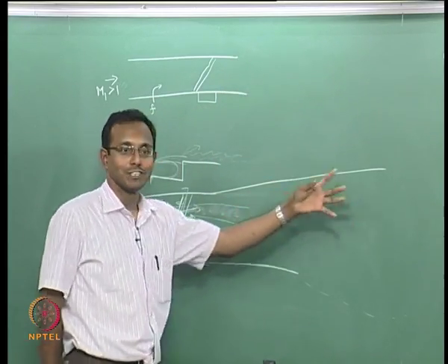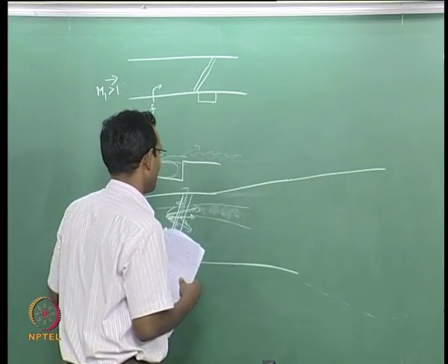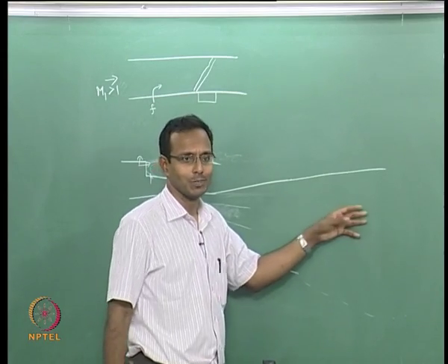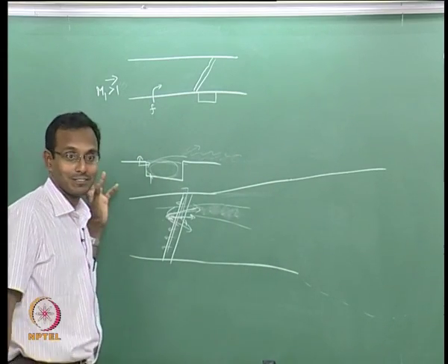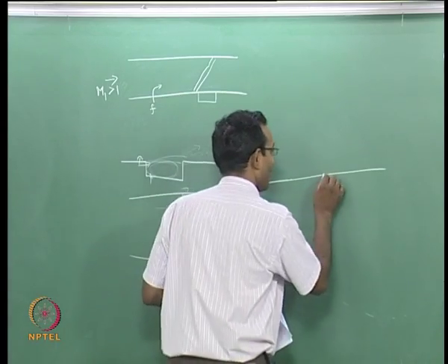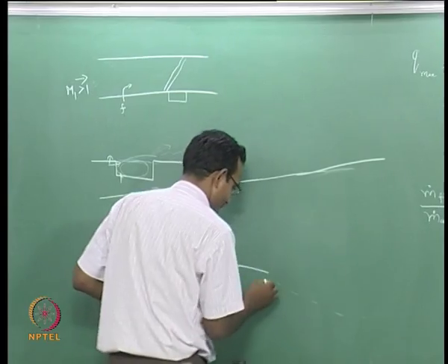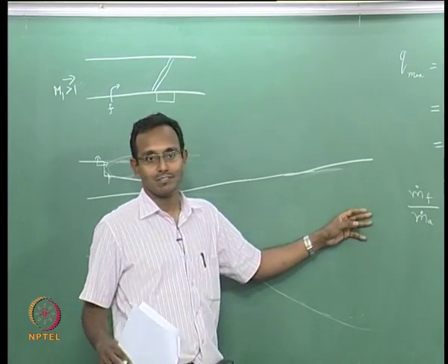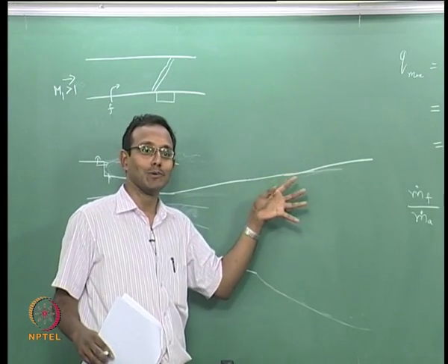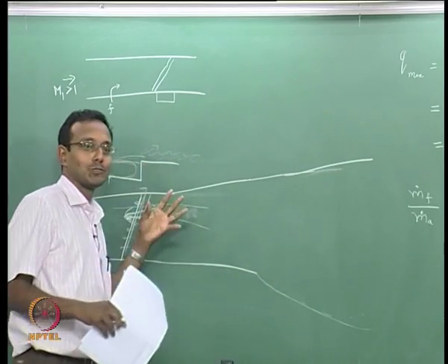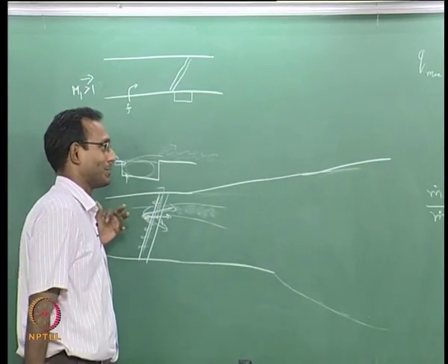Before that it has to finish all the job, that is the idea. Of course I do not want it to be exiting at m equal to 1, because I am flying supersonic, it is a scramjet. I have to think about having a nozzle here and a free expansion on this side to make the Mach number slightly higher than or equal to the incoming Mach number. I want it as close to the incoming Mach number as possible, I want to think about all that.